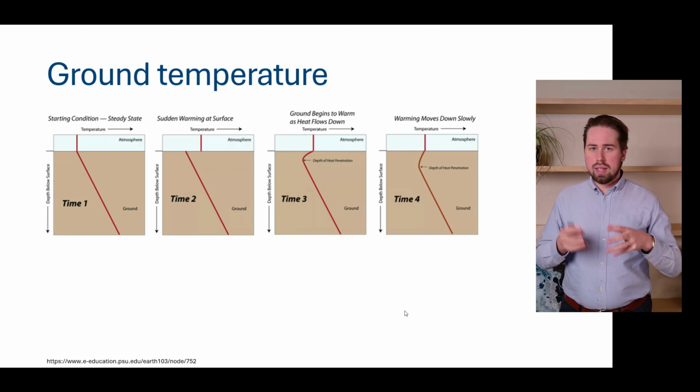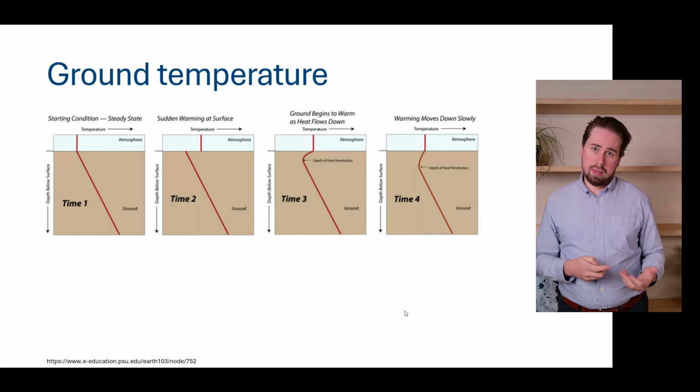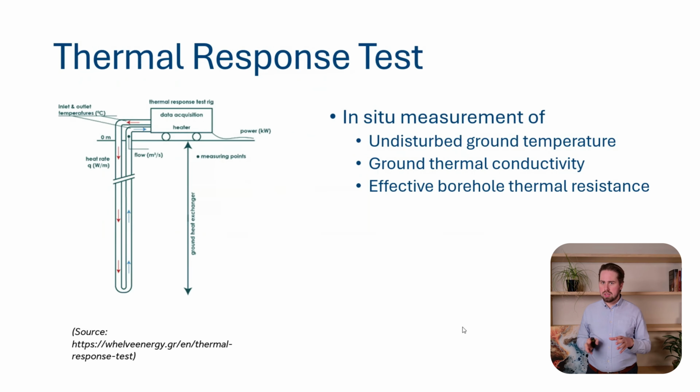And one way to solve it is just to do the measurements. And you can do this measurement with something which is called a thermal response test. We will cover it in more detail later in this course, but basically you install a borehole at a depth and the way you want to do it for the rest of your project. You're going to put a machine next to it that's going to measure the temperature going into the borehole and going out of the borehole, and you're just going to inject a constant power into the ground.